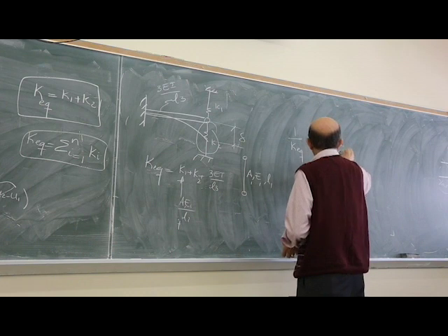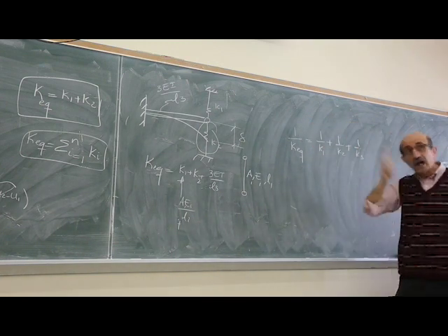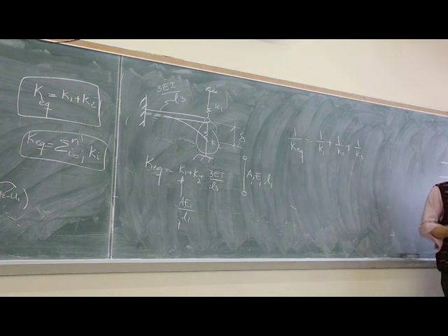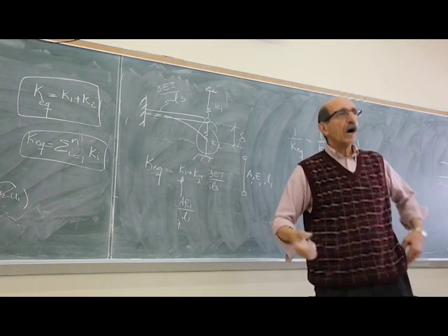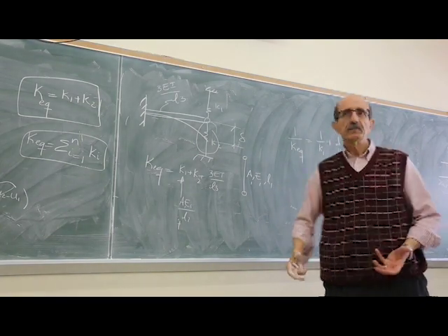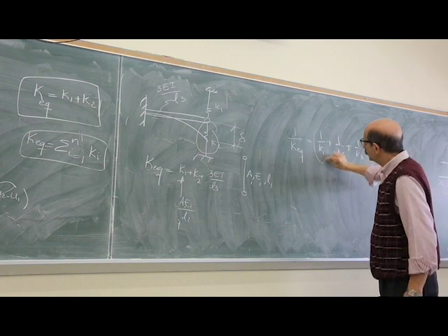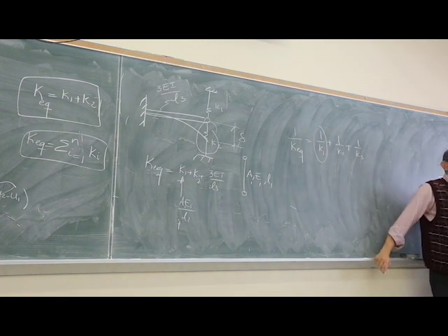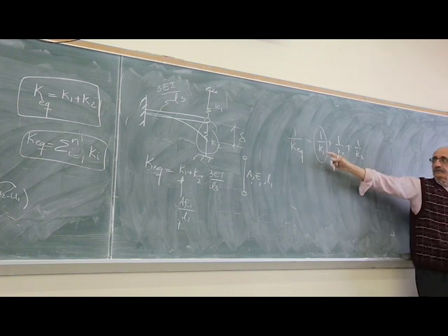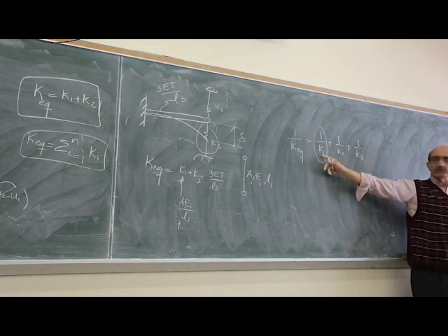You would be using this relationship, right? If you do not realize that these are in series and you want to avoid the vibration, you say, I'm going to stiffen the system by stiffening, for instance, this piece. If they're in series, and these are quite weak, if you stiffen this, what happens?